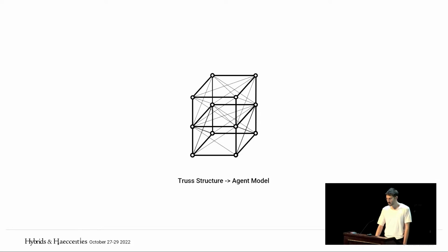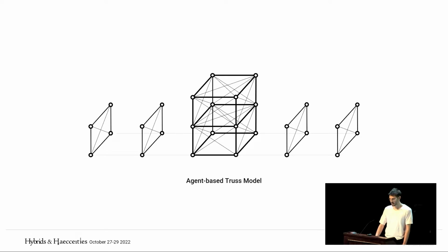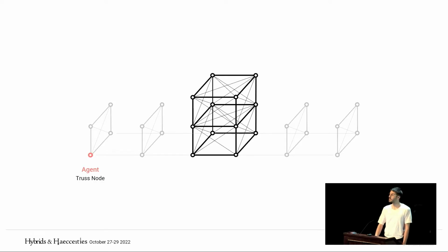The methodological challenge inherent to defining an agent model is the definition of what its constructs represent, as well as the abstraction of global design objectives to low-level agent behaviors. Our agent model is defined as follows. We define agents to represent truss nodes, whereas a truss element is represented by an explicit agent pair. Truss fields are represented by an implicit group of 3 or 4 agents, and an explicit pair of agents within or across truss fields define truss bracings.